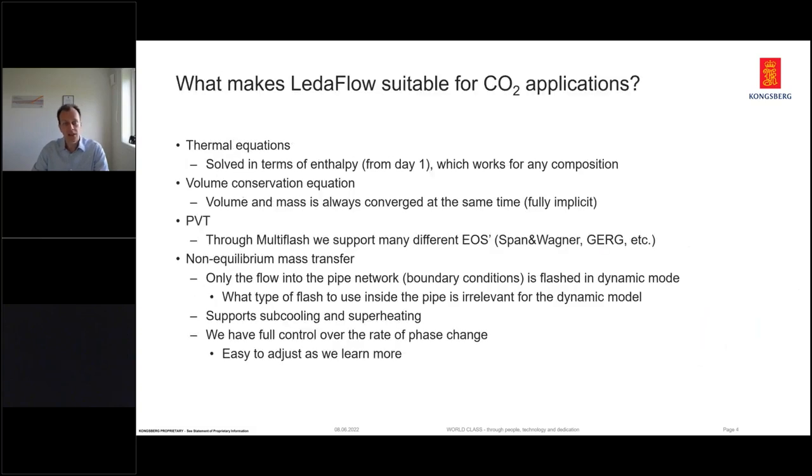Okay, so let's get back to: why are we doing CO2 simulations with LedaFlow? What makes LedaFlow suitable for this? Well, first of all, the thermal equations in LedaFlow have always been formulated in terms of enthalpy. So we conserve enthalpy. We don't have equations that are based on temperature, which is good because this is the only universal way of solving this that works for any kind of composition, whether it's an oil composition or natural gas composition, it doesn't matter. Pure CO2 also fine. So this is fortunate for us.